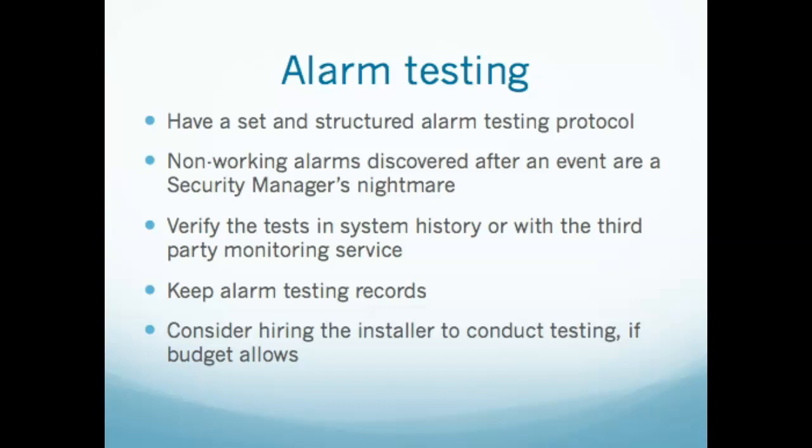Keep those alarm testing records, either the history in the system or a paper record that you did it, or had the third party mail you the results of the test every week, so you can keep them. But make sure you have those records because in the event that an alarm fails, you want to be able to show that you had due diligence at least every so often on your set schedule that you went out and tested those alarms.